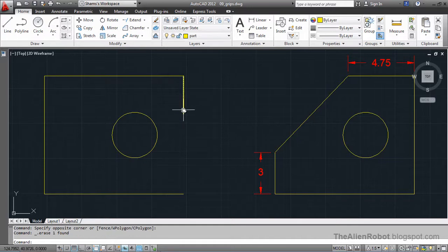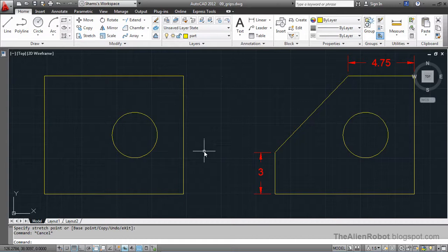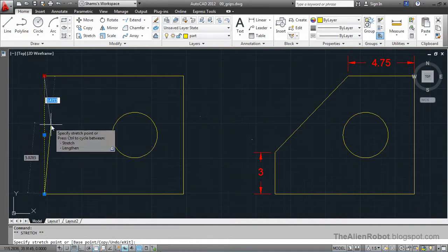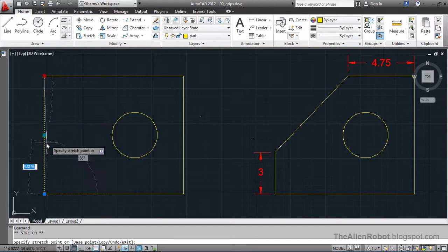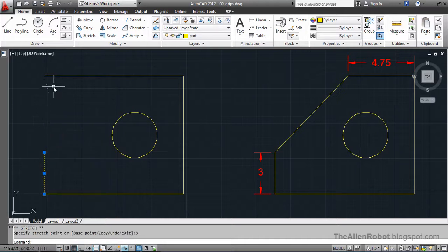these, and we're going to select this grip and snap it to this endpoint, as we don't need that head anymore. And let's select this line, this grip, and press tab to get to the overall length of that line and change it to 3 and enter. Press escape,